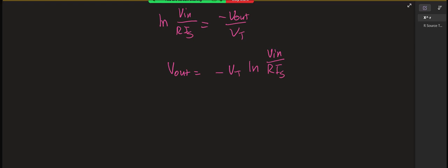Let me find another one. Yep. For the exponential diode equation on our formula sheet, there's a little -1 after it. You can usually ignore the -1. Okay, I just remember that. I don't have an answer for you, but I just know that you usually ignore it, because the changes are insignificant. Yeah, the exponential is so large, the -1 doesn't make much difference.